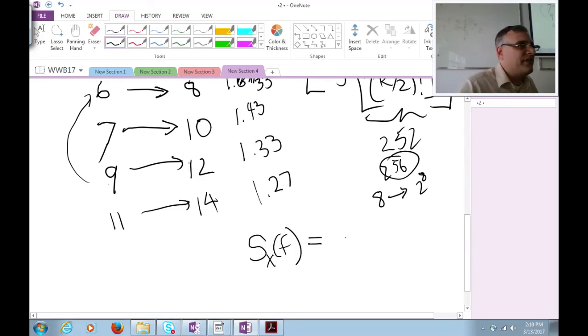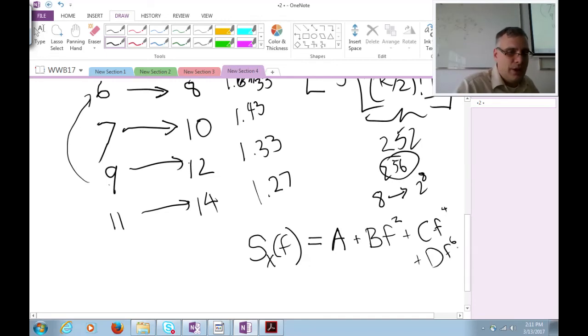you can view this as having a Taylor series, right? About 0. You can expand this and call this A. That's my DC term. Plus, there's a B F squared. Remember, there's only even components to a real valued power spectral density. So I should have some expansion like this. And what that balancing does is it always gets rid of A, my DC component. So I always get 0 at X evaluated at frequency equal to 0.